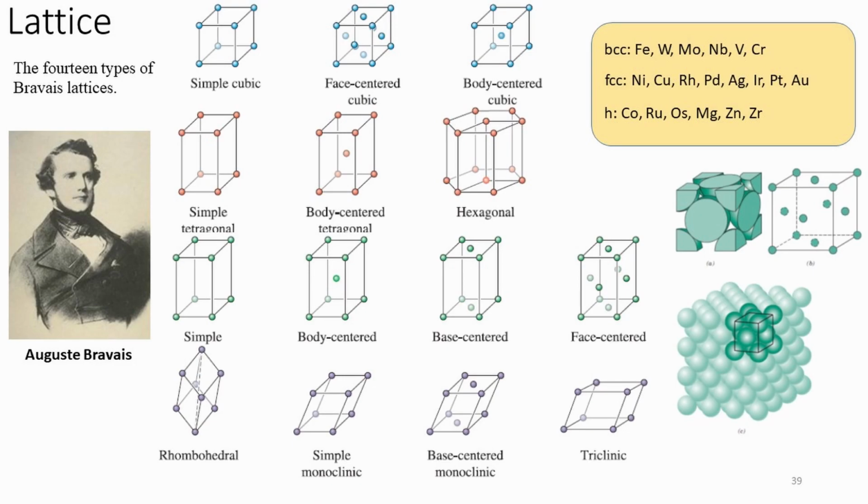In materials science and engineering, we use the concept of lattice to describe arrangements of atoms and/or ions. The unit cell is the subdivision of the lattice that still retains the overall characteristics of the entire lattice. Unit cells are shown in the slides. By stacking identical unit cells, the entire lattice can be constructed.